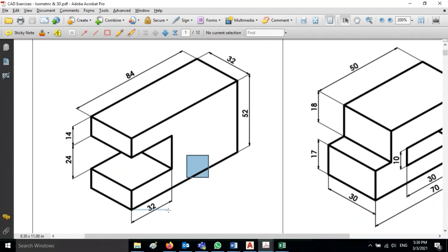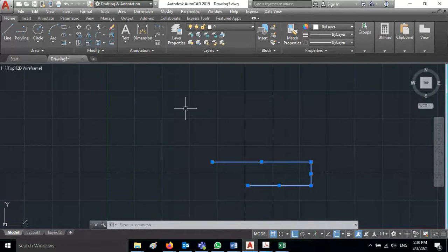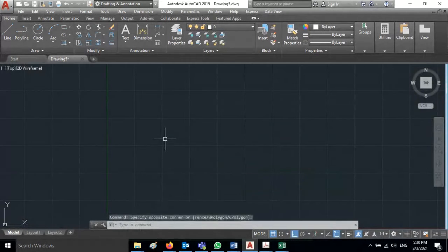Actually, this line will be from the horizontal surface. This is the horizontal surface. From the horizontal surface, this angle is 30 degree. Similarly, if you draw the horizontal line, this angle is 30 degree. Okay. Therefore, all the angles will be 30 degree each other, and this line is vertical. These three different lines we require. For that, you cannot do every time 30 degree accurately. We have another option called isometric snapping.